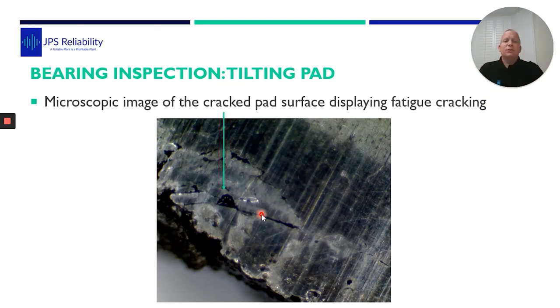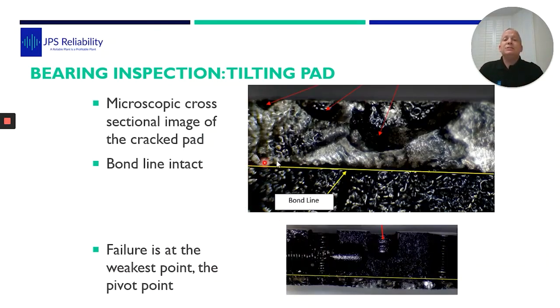So we turned it on the side and we can actually see the bond line was absolutely perfect. Nothing wrong with the bond line. And these little craters here was where the bit material was coming up. And coincidentally, it actually broke right on the pivot point at the middle. So with the tilting pad removed, the shaft is being non-eccentric motion, loading at its bearing, and it's cracked.